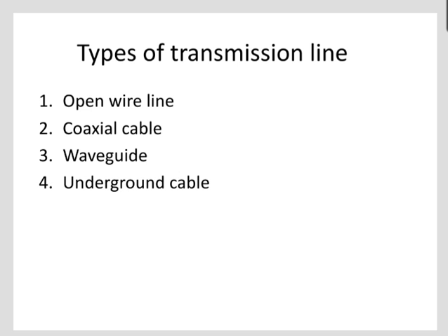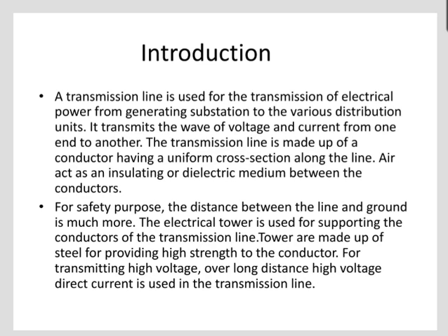The RF signals do not travel along wires or PCB traces in the straightforward fashion that we expect based on low frequency circuits. The behavior of an RF interconnect is very different from that of an ordinary wire carrying a low frequency signal. So additional terminology is used, and it is a transmission line. It is nothing but simply a pair of conductors that must be analyzed according to the characteristics of high frequency signal propagation.